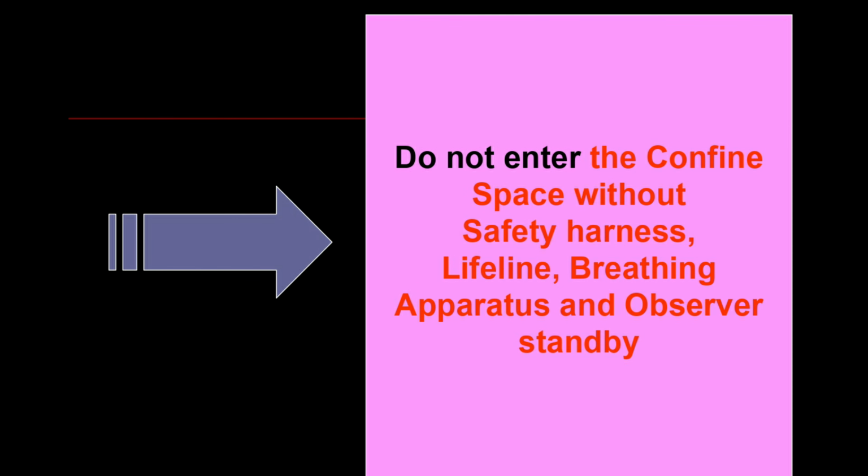Do not enter the confined space without safety harness, lifeline, breathing apparatus, and observer standby.